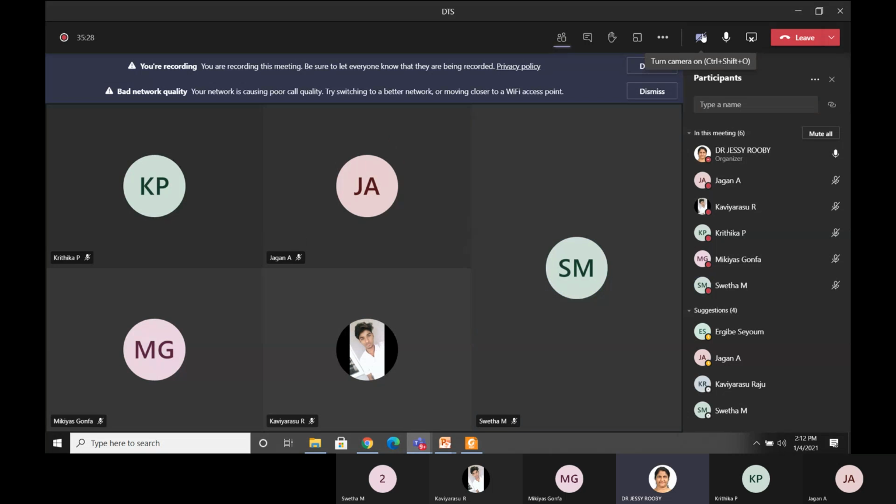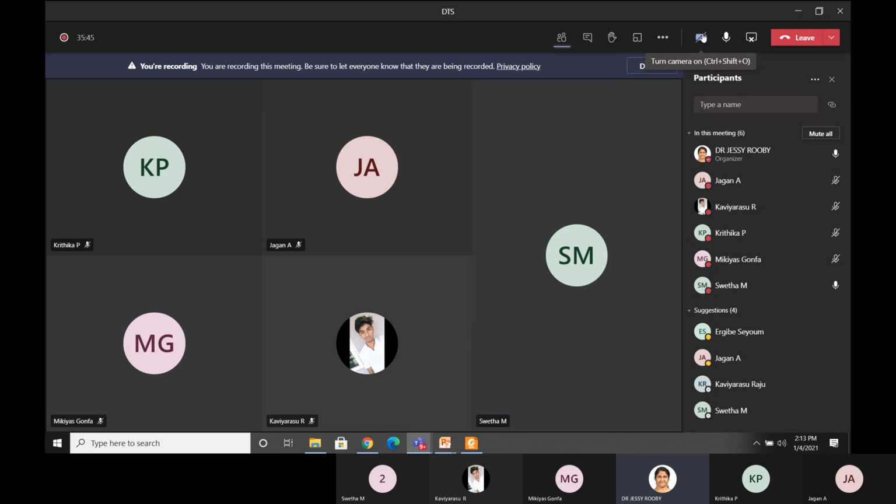Your R value will change from 3 to 5. Because when the R value increases, what will happen to AH value? It decreases, ma'am. AH will decrease. When AH decreases, what will happen to the base shear? It will also decrease, ma'am. Decrease. So base shear will decrease.